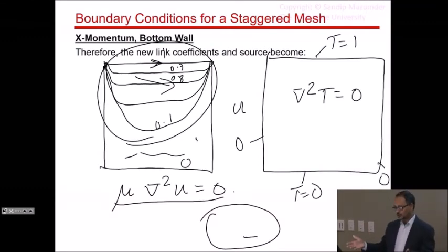So, why am I talking about all this? Because these are the things you need to look for in your code when you develop the code. You should solve your X momentum equation, and I'm going to tell you this again and again, go back and solve your X momentum equation very first time to machine accuracy and come back and show me the solution. If it doesn't look like this, then don't tell me that my Navier-Stokes equation is diverging and this and that, because you haven't even crossed the first barrier. Your first job is to get your X momentum equation working correctly. And this is what we called in the first lecture a sanity check. Getting this profile for U and 0 everywhere for V.